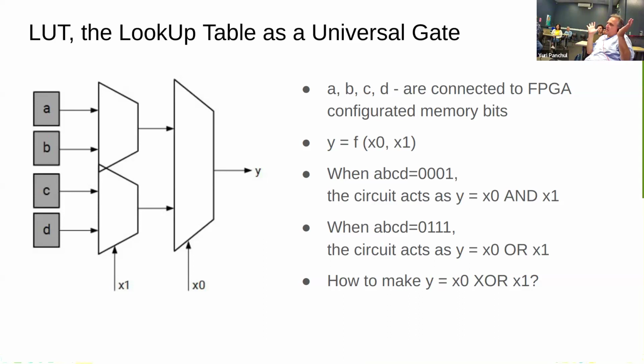You first need to synthesize your design for the emulator, compile it for the emulator, and then it runs hundreds of times slower: instead of 2 gigahertz, it will run at about 10 megahertz. But this is still much faster than simulation, where we are talking about a kilohertz.